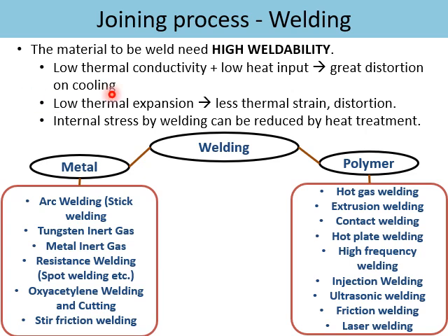Now, although welding is a well-known joining process, it is actually a much more complicated process since it involves heat. The requirements of welding depend on the material involved and the material's properties respectively. Only similar families of materials can be welded together, such as metal with metal or plastic with plastic. Ceramics definitely not, because it requires a lot of energy in order to melt it. In general, these are the methods for welding metal and plastic.